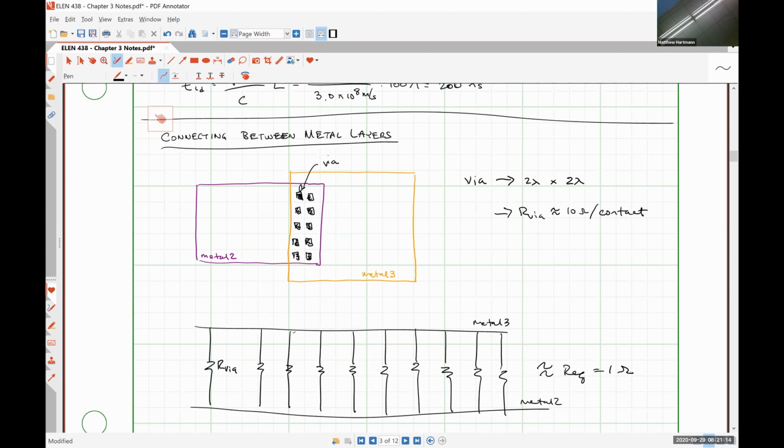So we've significantly lowered the contact losses between the two metal plates, which is good. We have now multiple points of interconnection between the two metal layers, meaning that if one fails, we're still able to pass a signal from metal 3 to metal 2 and vice versa. And yeah, so that's why we're going to try to use as many vias as possible whenever we get into the design process here.